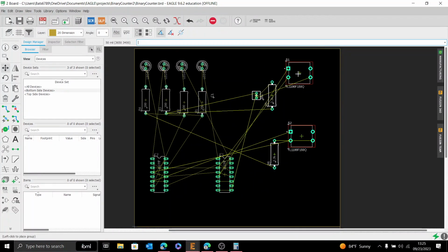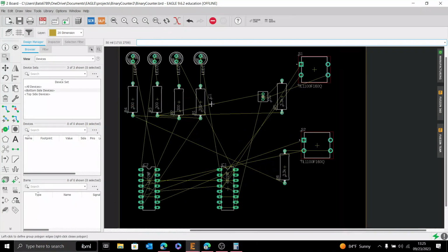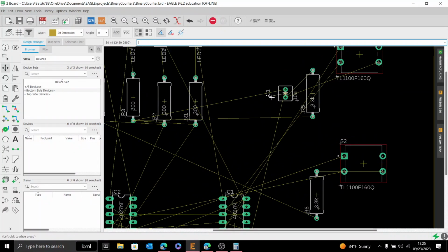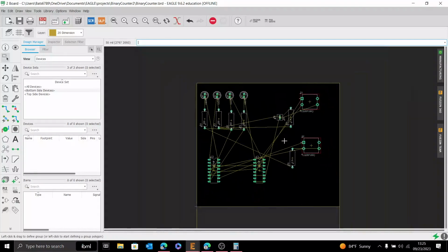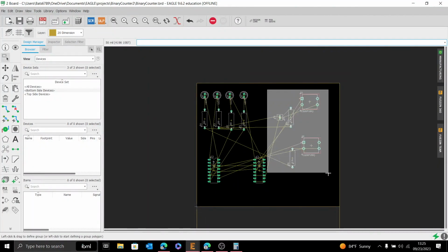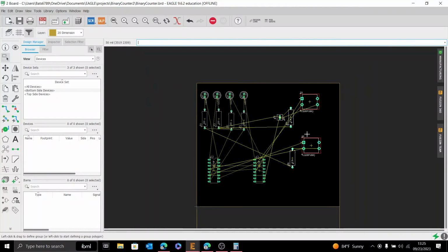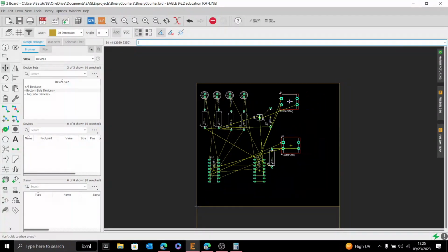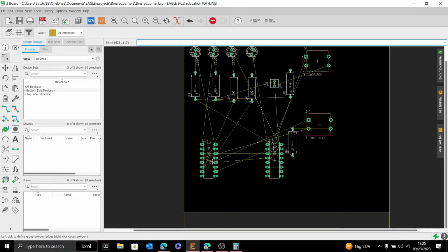And what's up? You could. That is definitely a possibility. I don't want to, though. That's my only justification, I don't want to. But yeah, you totally could technically run a wire between the two boards. As a matter of fact, once we go to the manufacturer page, you'll even see a way that you can segment your board. So it is not uncommon to have one layout with multiple boards, and they cut it in such a way that you can snap it and have multiple in one design.